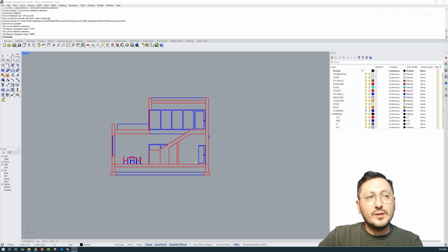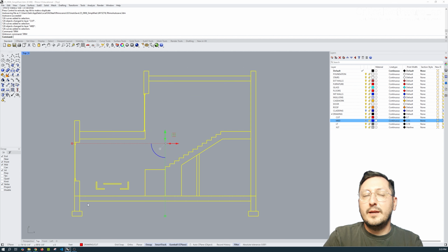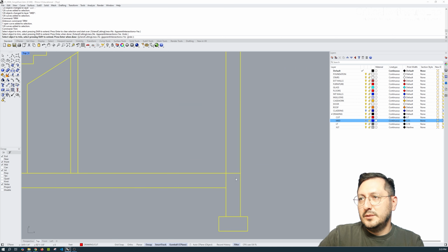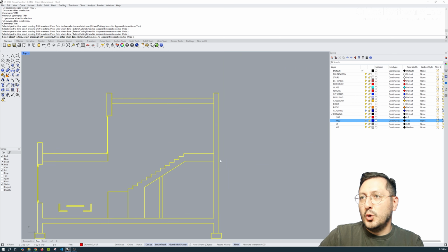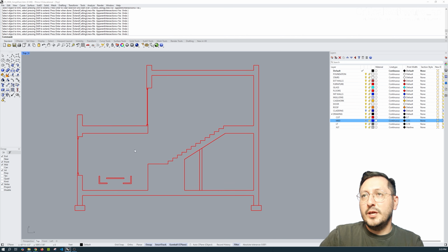The next step is to clean up the drawing, right? Because Make 2D doesn't really get us all the way there. And I'm going to go through and trim out any of the intersecting lines that I don't need. So things like walls that are joined that should bleed into each other. And so I think this is pretty good for a start of an orthographic drawing.